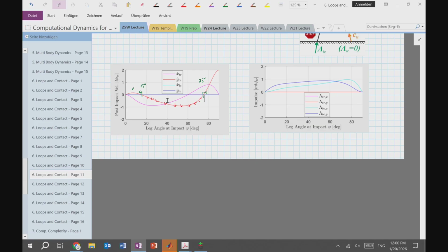It sounds weird at first, but if you think about friction as simply being an angle constraint, my friction cone doesn't say how large the force is, it just says in what range it can be. And here the angle becomes 90 degrees, and I still can solve this, still get some motion.